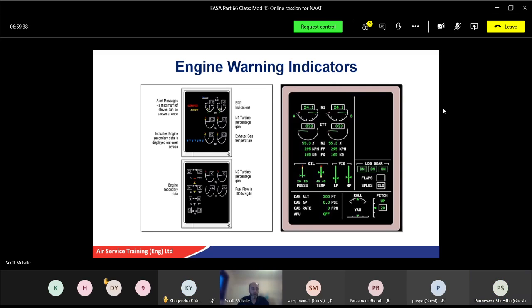And when does the pressure relief valve open? At what PSI? 55. No, a bit higher. When does the system pressure relief valve open? 90 psi. Yeah, good. 90 psi. Good. Okay. That one's done.